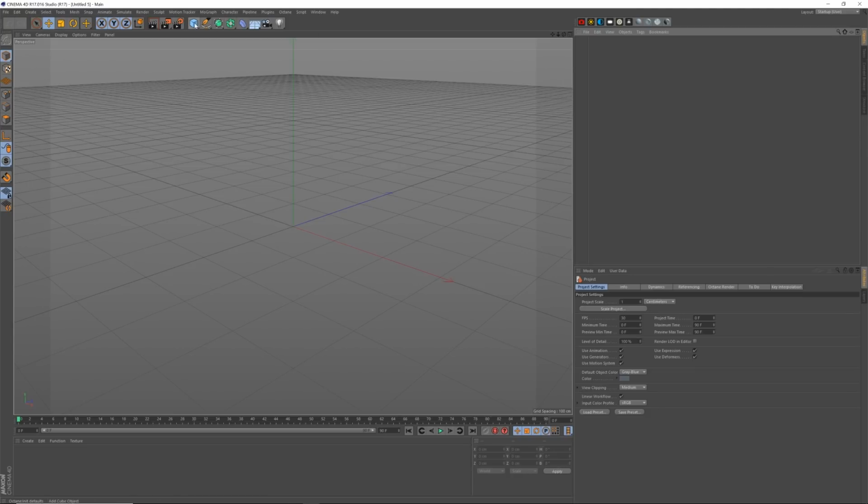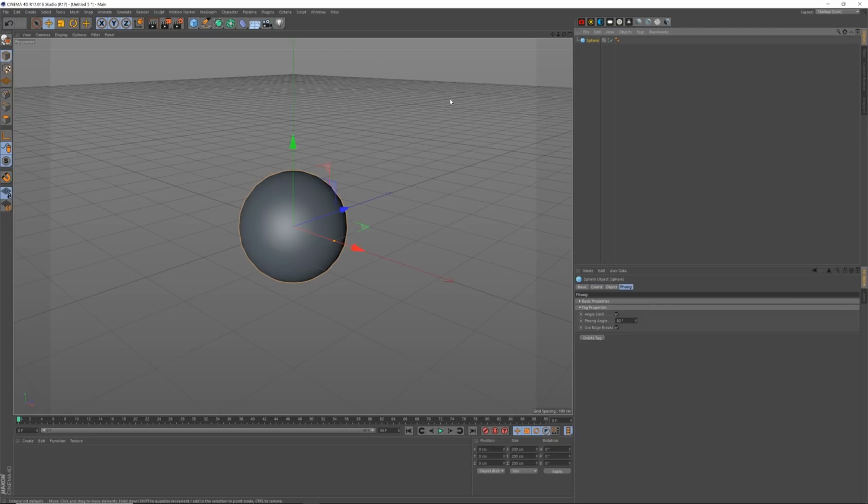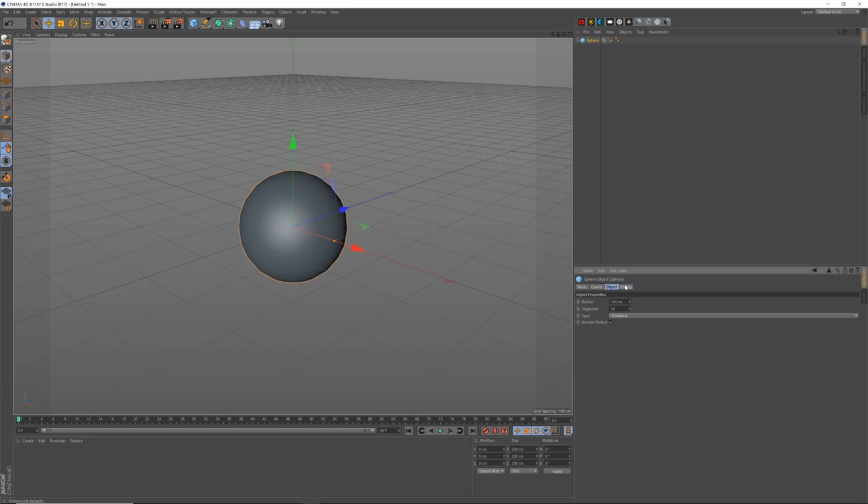First, I'm just going to select the objects, go to sphere, just so I've got a basic object that my whole scene will rotate around and it's in the default center position. So if I select object, turn off render perfect, segments to 48.